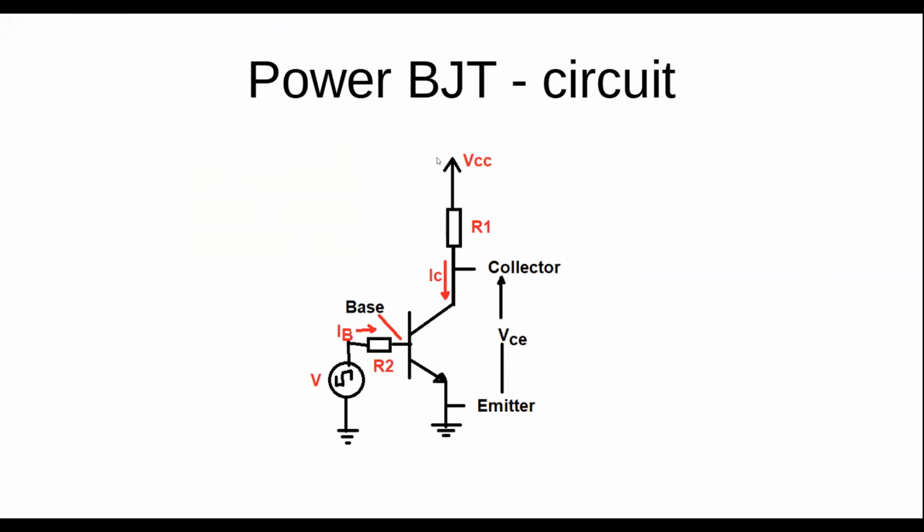Okay, so this is the symbol. We're doing NPN, and we always talk about NPN, it's sort of easier. Most of us are used to the NPN. This is a resistor, that's basically our load. When it's forward biased, I've got this current coming down, and this current is positive. If I push it into saturation, then everything is forward biased, so I can have a large collector current flowing down into the emitter.